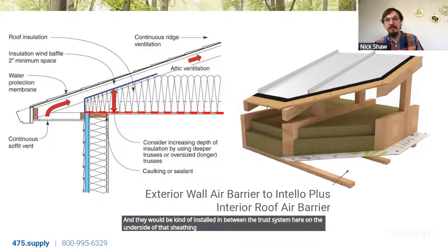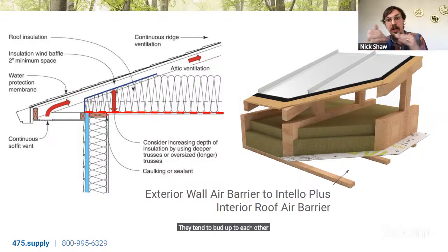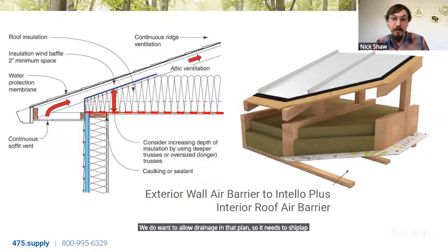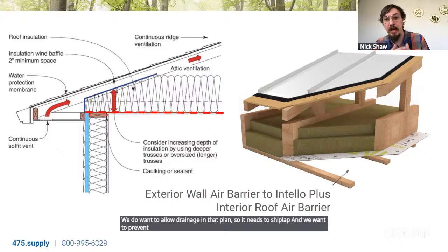My concern with the foam baffles is I rarely see them installed properly. They tend to butt up to each other and not shiplap. We do want to allow drainage in that plane, so it needs to shiplap. And we want to prevent air transported wetting, i.e., the outside air getting in and around those baffles into our